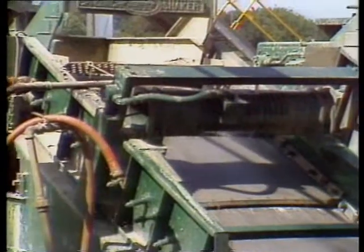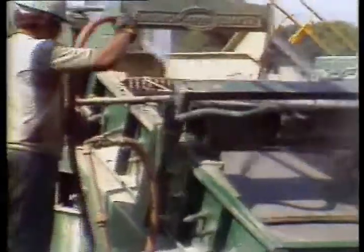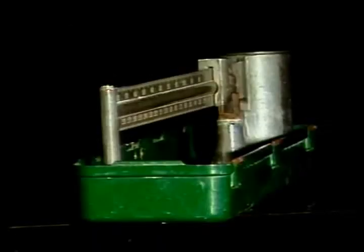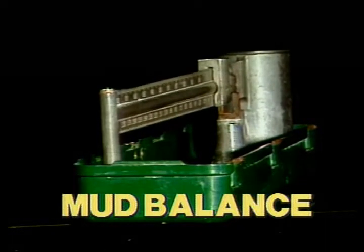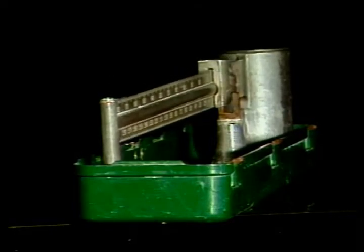Another common problem is somebody washing down the shaker screens, like this. This can add too much water to the system. Whatever the reason for changes, the mud weight is important, so your tests have to be done regularly and accurately. And both you and the mud engineer will be taking the weights. So naturally, a scale is needed, and you've probably already been introduced to a mud balance of some sort by now. But I'll bet you didn't know that every week or so you should check it for accuracy.